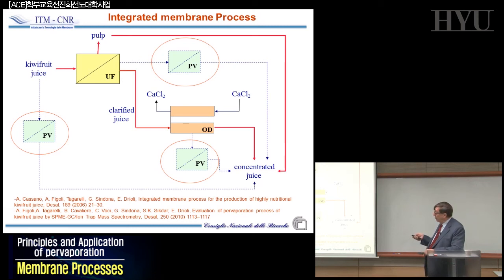But for doing this, you have a problem. And you learn that when you make membrane distillation, you want to use normal technology at room temperature. You don't want to destroy the aroma, nothing from your wine or from your juice, so you have to avoid temperature increase because you lose everything, you destroy all the aromatic part, etc. So you can clarify first, and after you go to one of the techniques, membrane distillation.